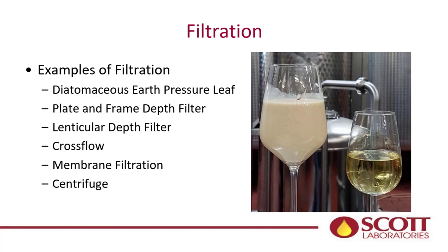And this is another representation of it. This is a pictorial representation on the right-hand side there of a lees filtration. So after you've racked the majority of your wine off the lees, this would be taking something that's really high in solids and clarifying it with either a rotary drum vacuum filter or a DE pressure leaf filter, maybe even a high solids crossflow, and you can recapture the wine that's in that lees.